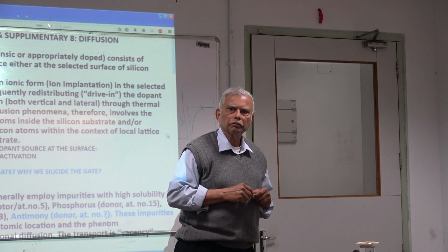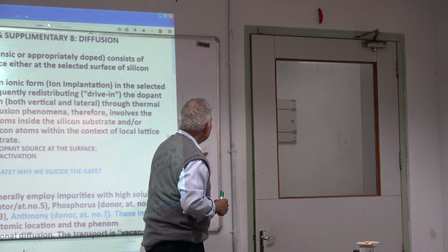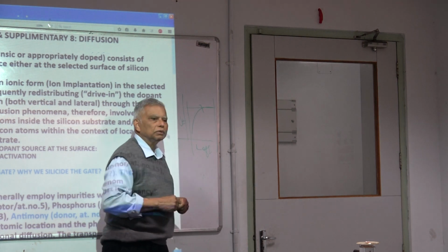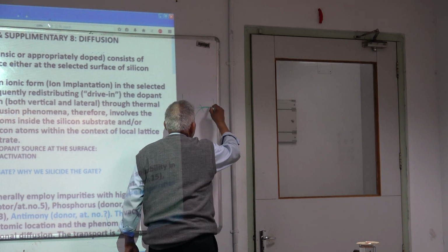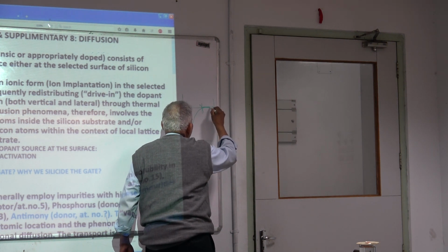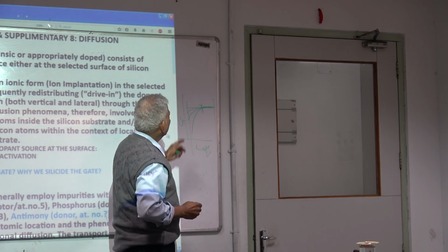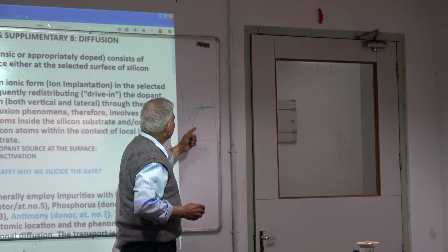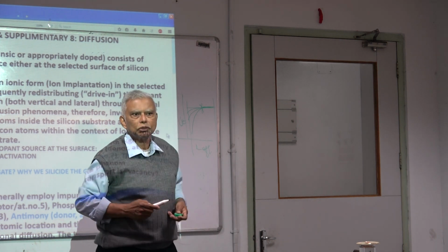Drain-induced barrier lowering. They move up, they make this effective in the range that the design technology allows, depending on how nicely you can do this. In other words, a superior technology would be this, an inferior technology would be this. That's how important the short channel effect is.